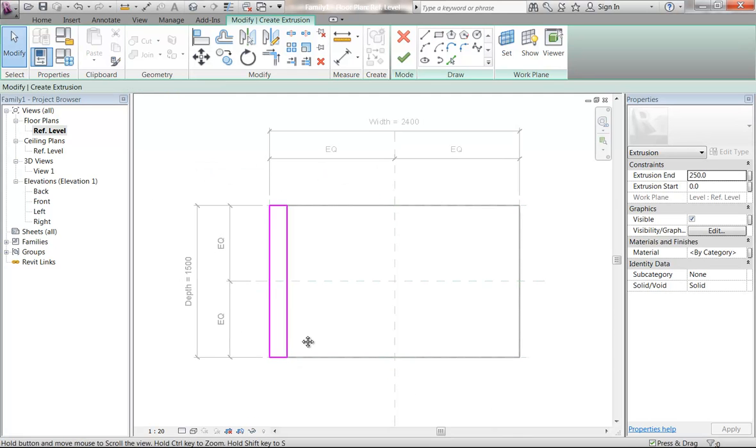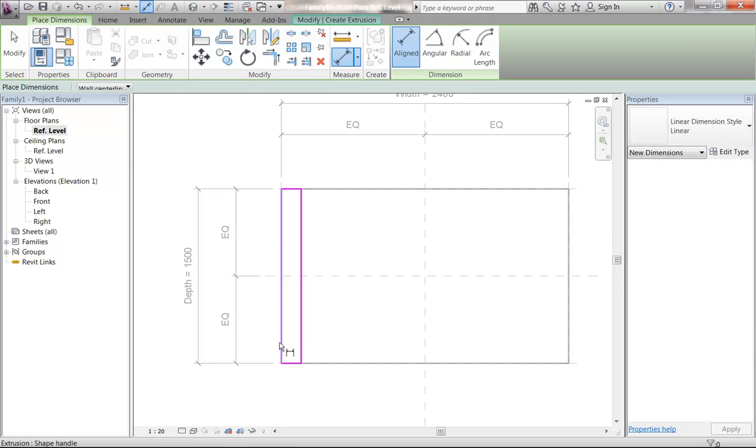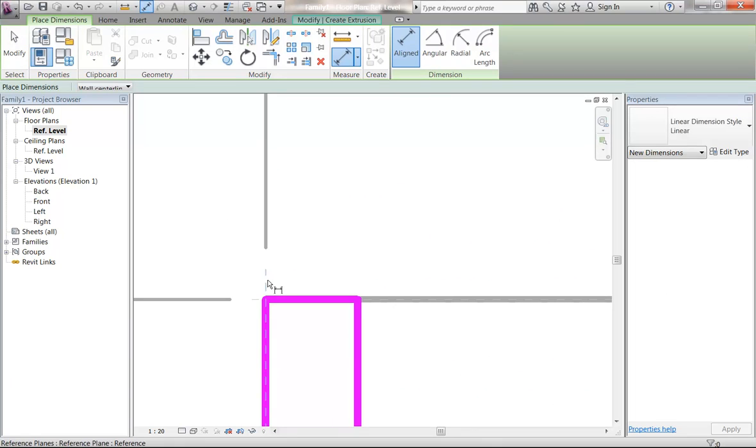Okay, so remember I made the thickness parameter already for the desk thickness. So we always have to lock it to things that it needs to be locked to, so just think about where it needs to be locked and where it doesn't. So here I can draw a new dimension now from this edge. Now again, remember I've got the reference plane along that edge. So it's always best to get the first reference. The reference plane is the thing that has the width set to it. It's the element setting the width essentially.